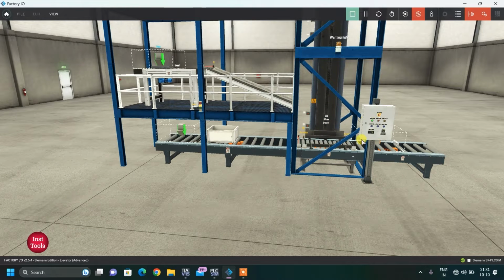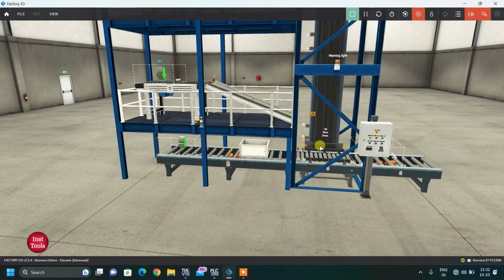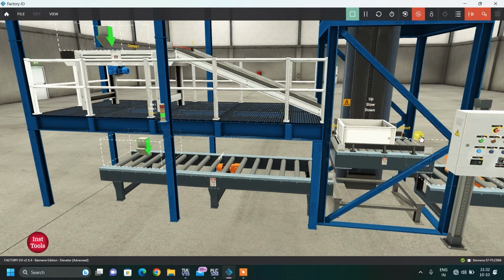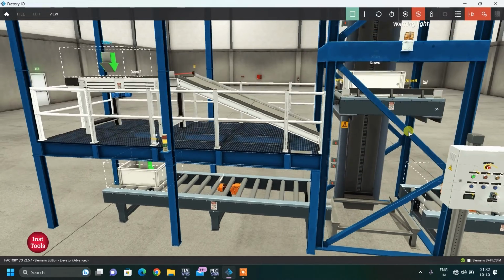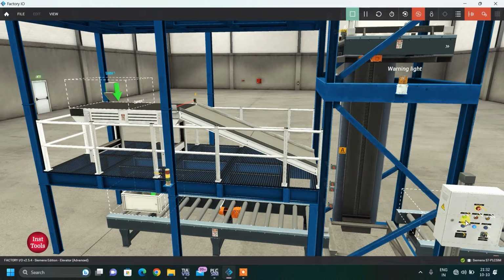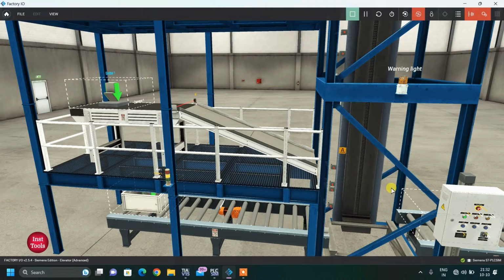But when we are unloading, you observe the direction of this conveyor is the same. It is the same as the loading, okay, this direction. So while unloading also, we will turn on this output only. So you saw I didn't press any button. It started automatically. Besides that, in this project, we have also written code for different indication lights.